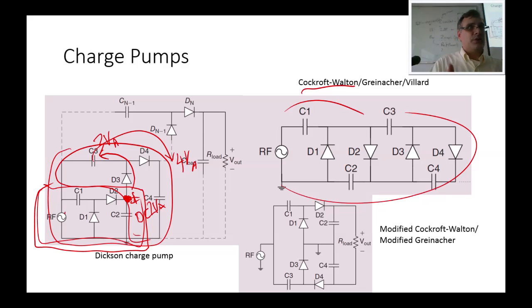They built a charge pump, literally a bank of capacitors and mechanical switches that would switch up and down, charge up a capacitor with DC, and then ladder it up. You charge up another capacitor with DC and ladder it up, and it would mechanically step up the voltage. So you could turn a small DC voltage into a very high DC voltage, and then simulate a bolt of lightning, or in their case, I think they were accelerating a particle to a very high velocity.